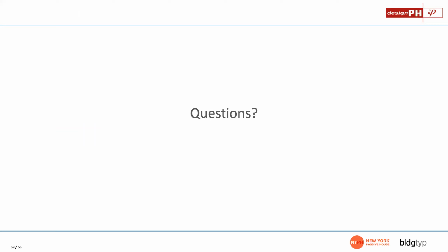So Matt asks, can I save as the blank PHPP before populating it with PHPP data? Yes, you should do that. If anything errors during that import process, say the power goes out, you don't want it to corrupt that source PHPP. You always want to keep that source PHPP clean and uncorrupted.